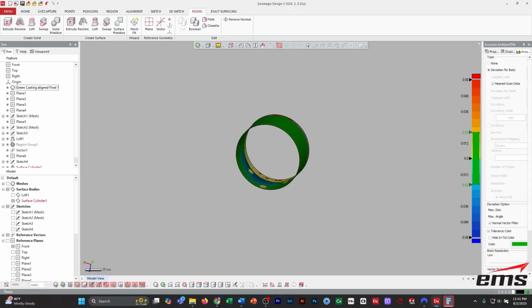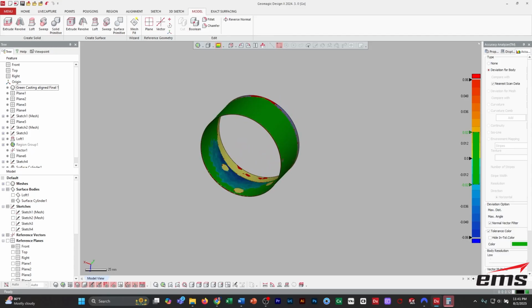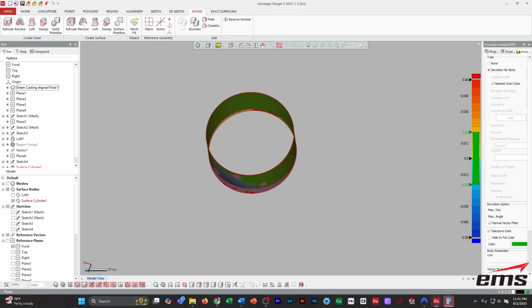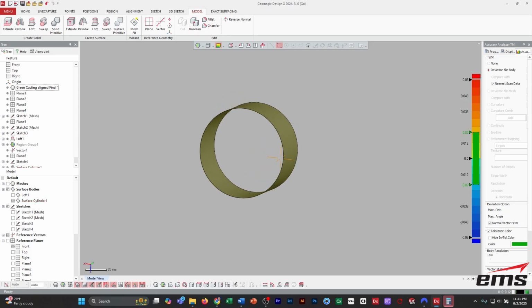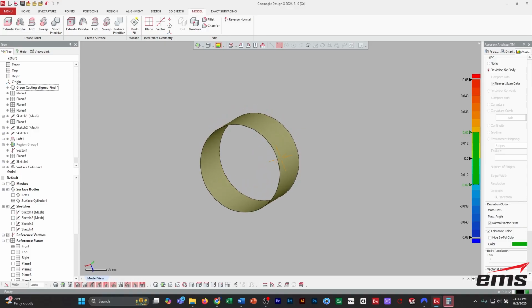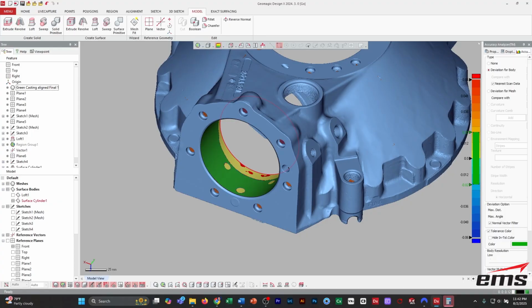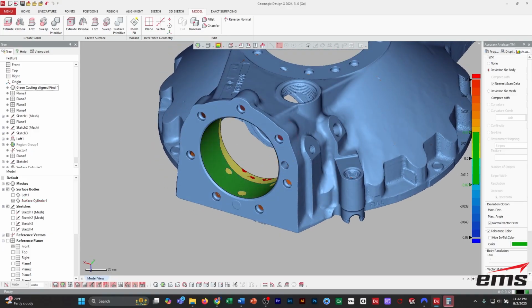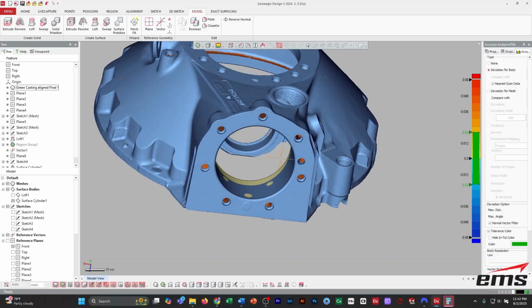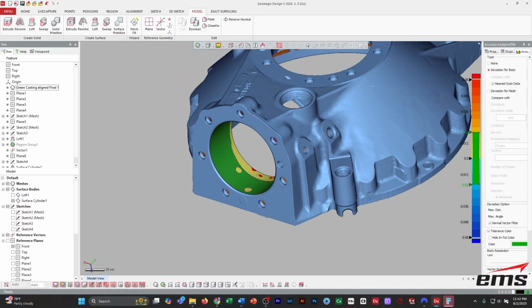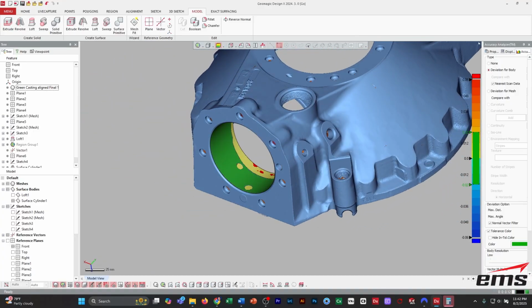Okay, so you can see, and we'll keep the same tolerances. You can see in this area, it's off by 40, 48, 50 microns. Up in here, it looks pretty good. So the only thing to keep in mind is what I was alluding to: that cylinder is just best fitted through there. We're not measuring where the axis of the cylinder is in relationship, although I think that's something we can do, and maybe we'll try that out. And knowing this is on an angle, but let's just stick with this for a minute.